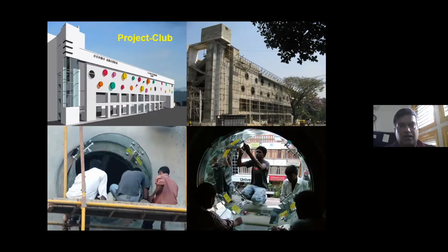Again, there are people, this is just below the main walkway, below the footpath as we call it, and any breakage and falling down could easily injure and probably even kill people. So what was done is, in this case, we used the 3M interlayer, and the 3M interlayer had the capacity to hold on to the glass even if it breaks. So that was the concept that was used.